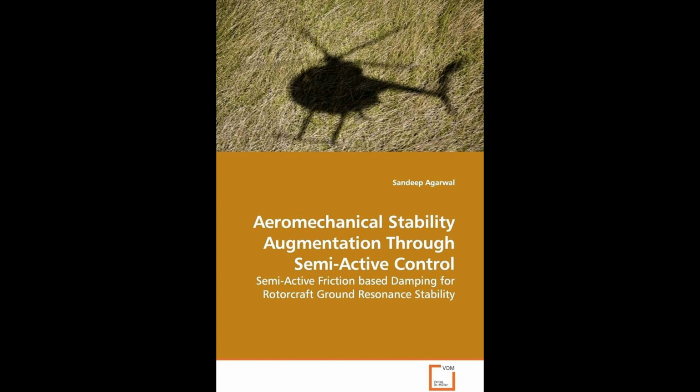Helicopters with complex automatic flight control systems, AFCS, and autopilots normally have a trim switch referred to as beeper trim. This switch is used when minor changes to the trim setting are desired. Stability augmentation systems reduce pilot workload by improving basic aircraft control harmony and decreasing disturbances. These systems are very useful when the pilot is required to perform other duties, such as sling loading and search and rescue operations. Other inputs such as heading, speed, altitude, and navigation information may be supplied to the computer to form a complete autopilot system.